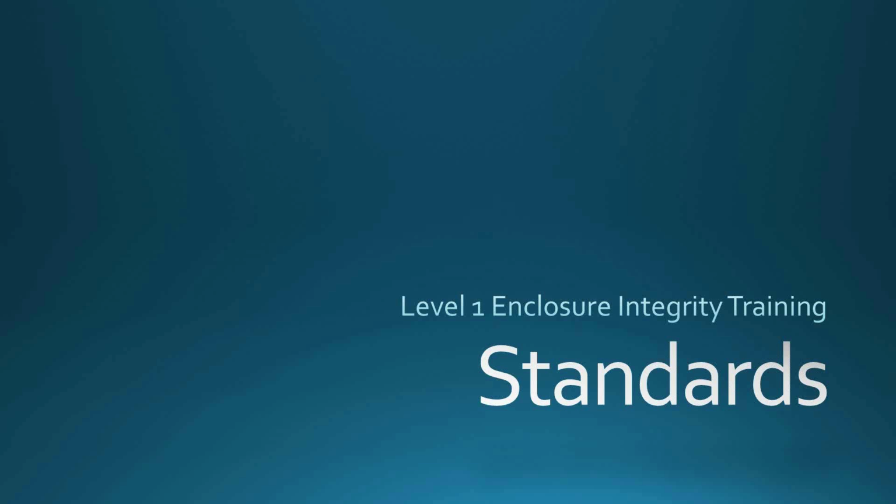The ISO uses what we call a wide interface, which says it starts at 0, and as the interface drops, it keeps expanding. We've discovered that's not actually the case. The interface expands to what we call a characteristic thickness and doesn't really expand beyond that. And for halocarbons, it's about 0.5 meters or 1.5 feet, and stays at 1.5 feet as the interface descends all the way to the bottom of the enclosure.